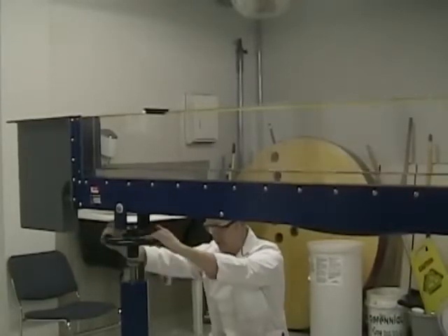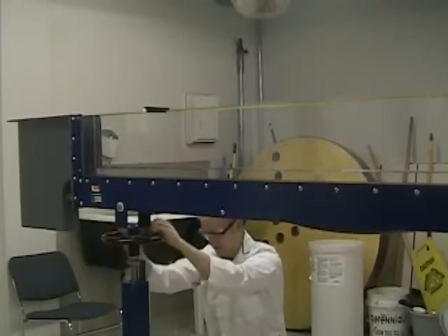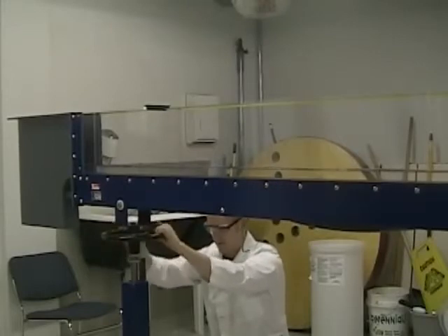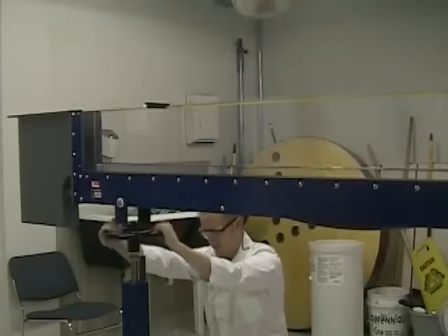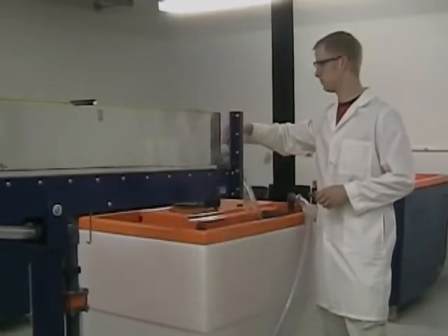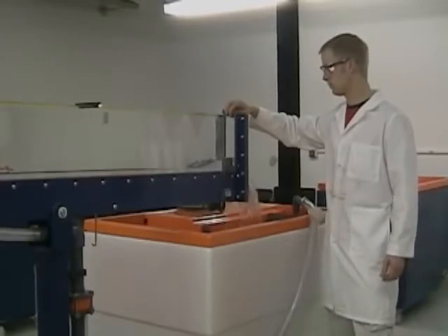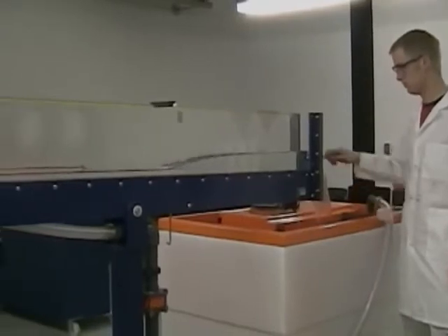We are going to increase the slope. Take a moment and decide whether the critical depth line should be raised, stay the same, or be lowered. You're right, the critical depth does not change since it is only dependent on the flow rate and geometry, and neither was changed. We can see that increasing the flume slope has decreased the normal flow depth, such that we have supercritical flow. Since we already have supercritical flow, all that we need to do in this case is cause subcritical flow downstream. This is done by inserting stop logs at the outlet.